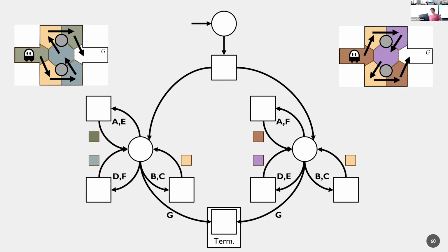We take this action that non-deterministically transitions to one of these two action-based sensors. This transition left or right encodes a single bit of state, that of which path our robot decided to take. And that is actually all the state this robot needs to solve this problem. This robot needs one bit to remember what choice it made, and that is all.